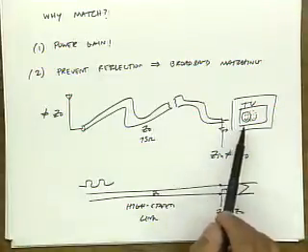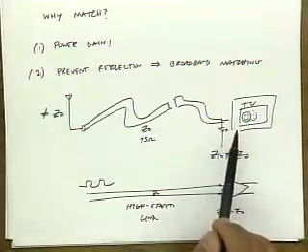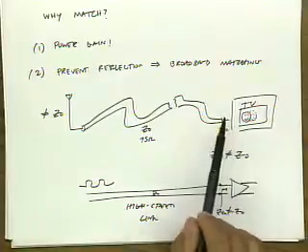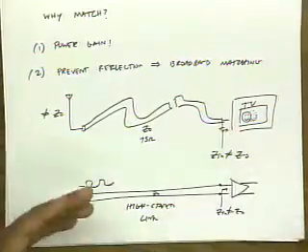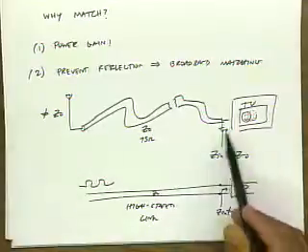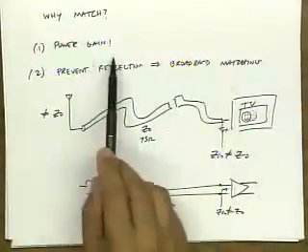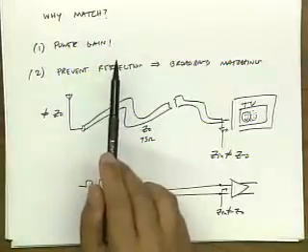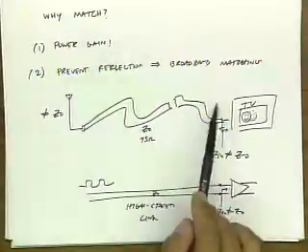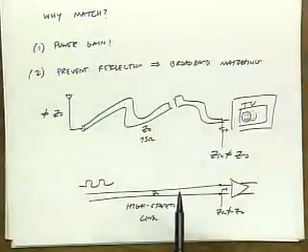Whereas here, for the television signal, maybe if we're just watching one channel, we could stand a narrowband match. But if you want all your television channels to look equally as good, you want a broadband match. So there are cases where we just care about one frequency, kind of like maximizing the gain of a narrowband amplifier, and there are other cases where we'd like to get a broadband match.